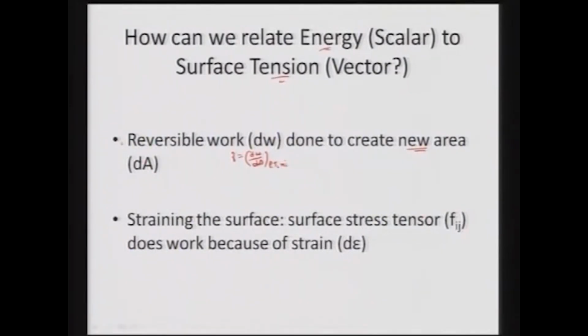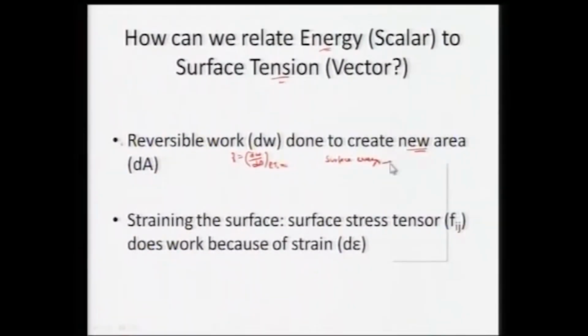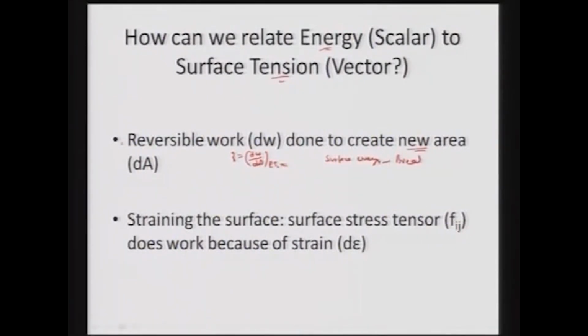Whereas in the second case, if we consider surface energy, we need to break the bond. So for surface energy, we are breaking the bonds, and we are getting some enhancement in the free energy per unit area of the new surface which is being formed. So we can see that delta G is equal to gamma times (A2 minus A1), when A1 and A2 are the two equilibrium states, basically while keeping the pressure, temperature, and N1 constant.